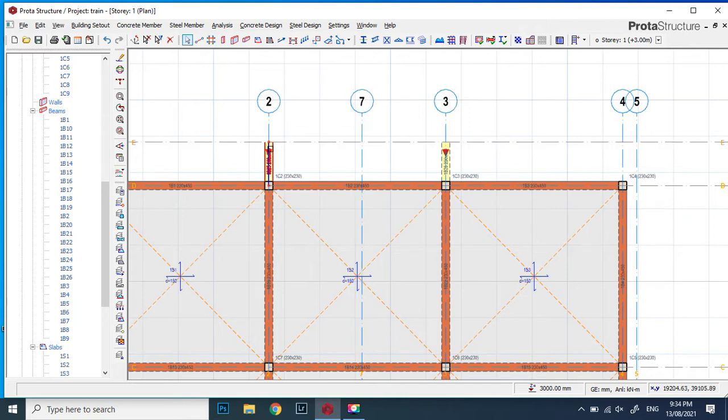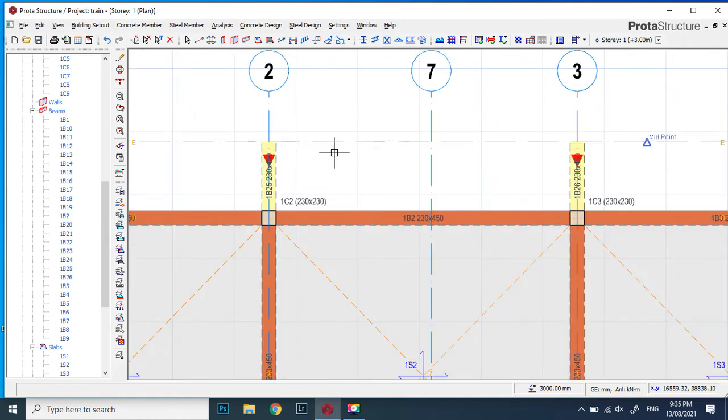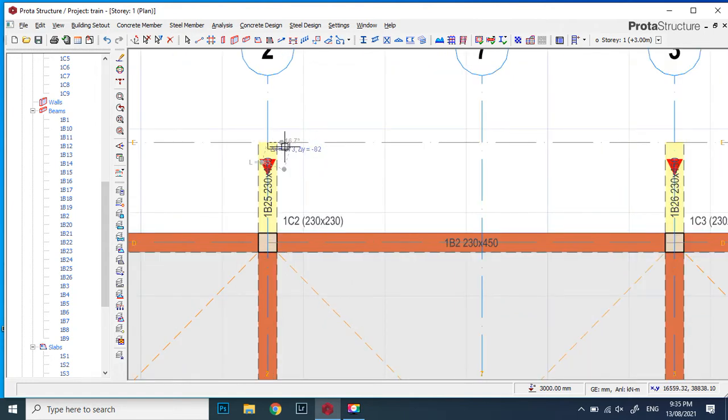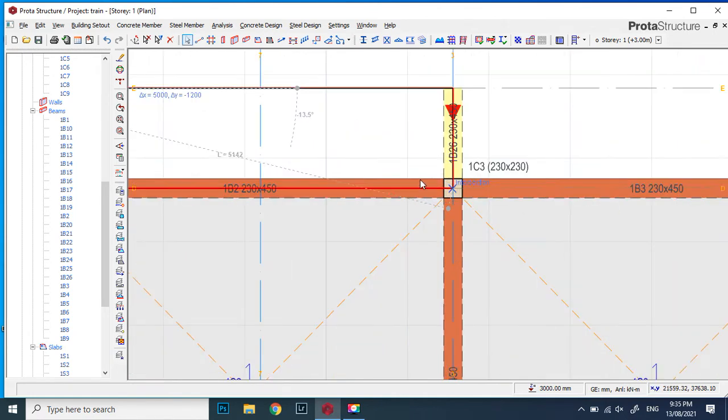If you have something like this, what you do is you come to slab stroke column edge, line stroke arc. You come to this part from your menu bar, slab stroke column edge, click it. You see different options to use: line, arc, rectangle, circle. But we are using rectangle. We click on rectangle, and please pay attention, click on the intersect of the grid lines to the next intersect.